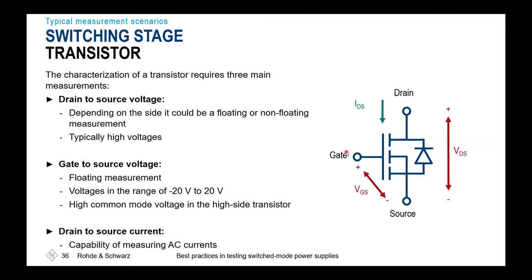So adding a high voltage differential probe without a galvanic isolation could cause you ringing effects at the gate source and might lead to destruction of your device, due to the parasitic couplings inside the probe. So that's why it's important to be aware.